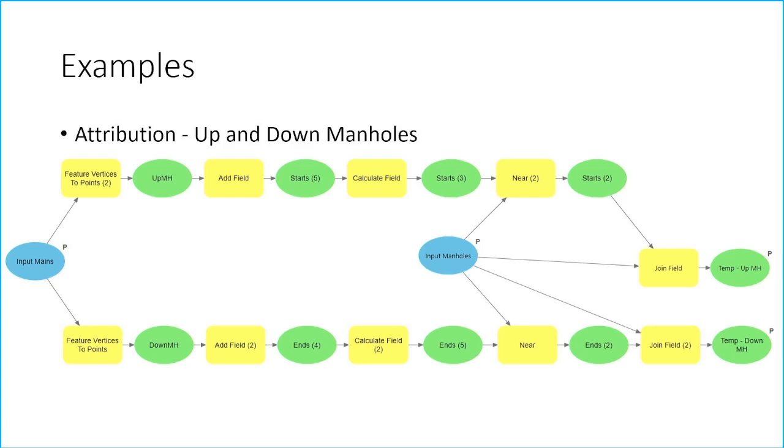Your GIS administrator will be ready to shoot you if you do a near. There are a couple different near tools. A near will do the near and it'll append fields onto your data. But the near table is a separate option. A near table actually creates a table that does basically the same thing, but it's not putting those fields on the data you're feeding into that tool. So just be careful what tools you're using and what they're doing to your data.